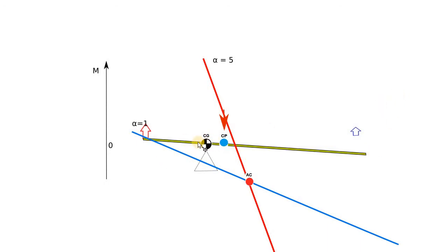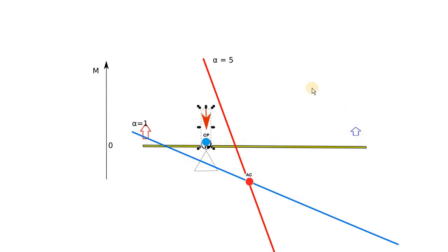But the center of gravity stays in front of the center of pressure. And if you look at this position of the center of gravity, we have a bit less of a nose, but more of a tail. So the system is stable because we have an extra section which is going to be acting about this axis. In that case, the tail is going to be acting in the opposite direction, trying to restore the original angle of attack. So it goes back, and the center of pressure moves back to the original state.